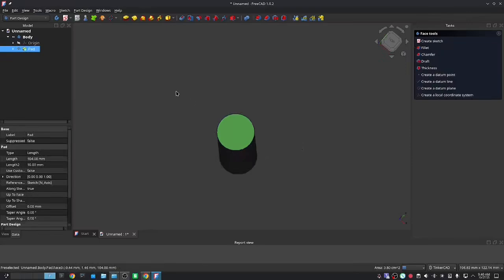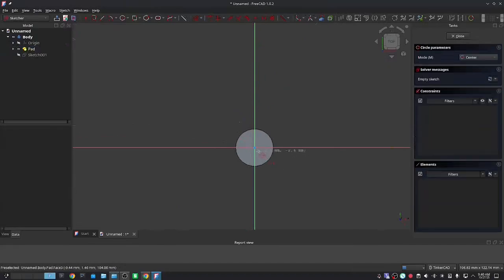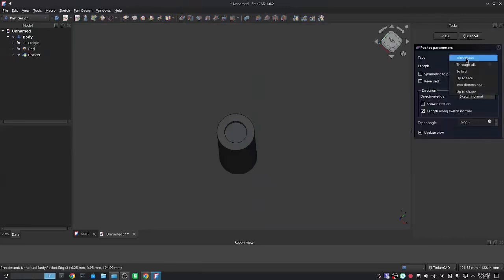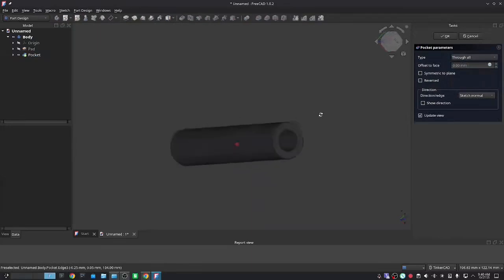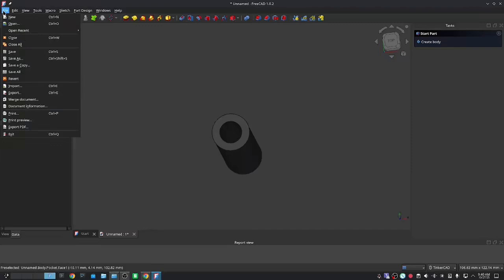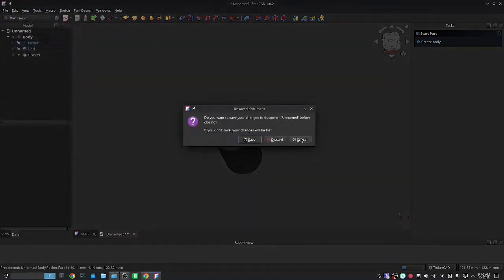So I want to click the surface of this, want to start a new sketch. Make a circle that's 13 millimeters. Hit the end, not 132, 13. Hit enter. We're going to close that sketch. We're going to make a hole. We'll change the type to through all. And this is just a sleeve to go around the axle for the hub, for the wheel to ride on. That's done and ready to print. We'll send that out to the printer. And we'll start working on the motor mount.